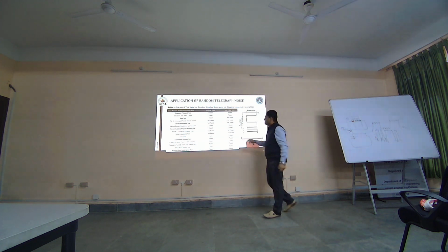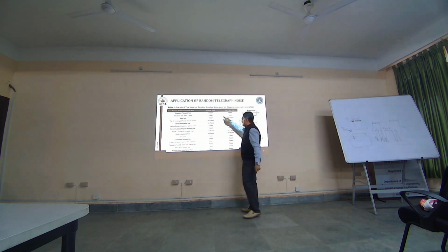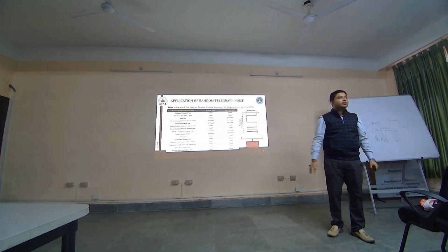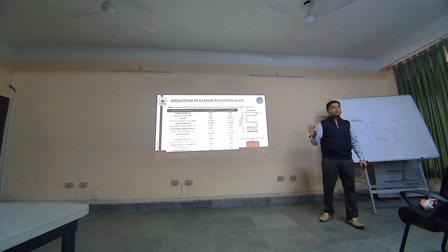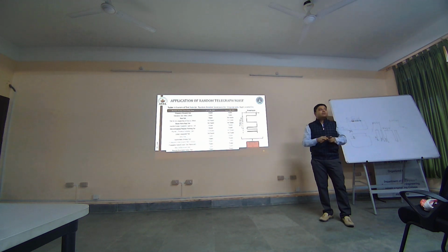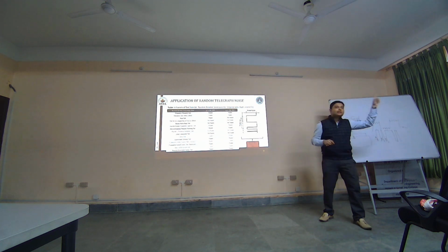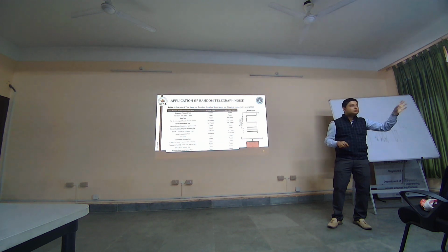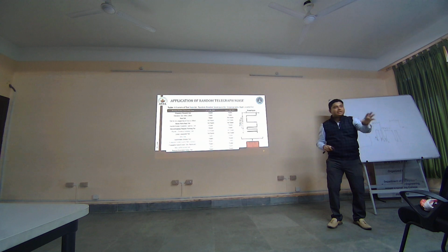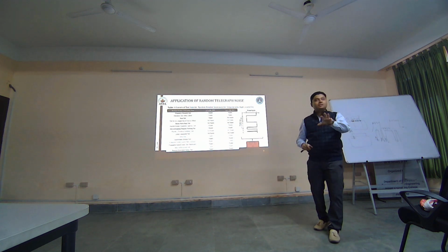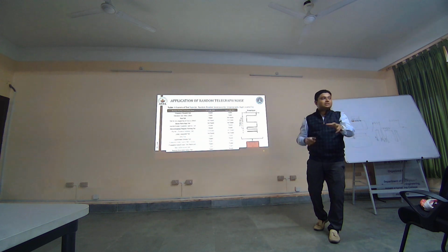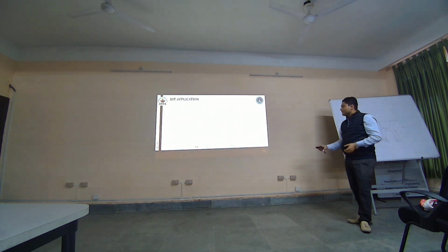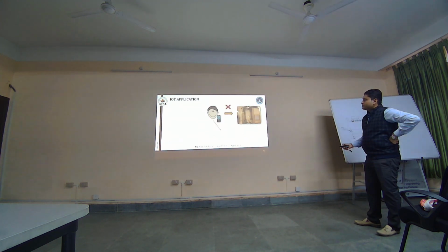Okay, so we tried to do this for both the devices, and I think in one it passed 11, and in the other it passed, I think, 10 or 12, something like that. So basically this is okay to be a random number generator. If you observe the timeline, we started with a single trap just to see whether a single trap can have an effect. Then we found out that due to a single trap you can have RTN. Then we realized that using RTN we can go for random number generation. And since you cannot simply convert it, we also did these kinds of tests. So this is the application which we are doing.